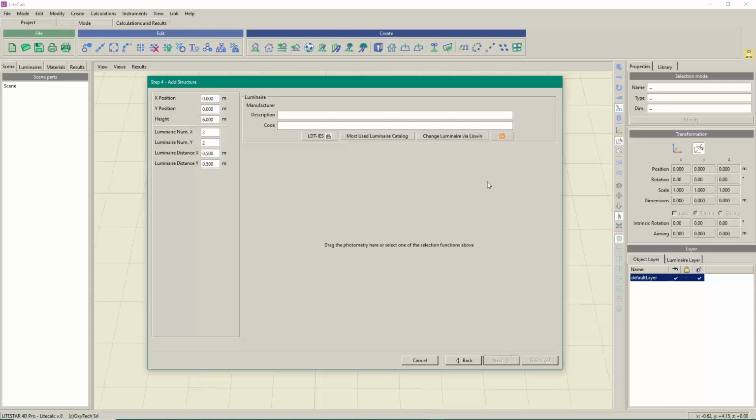So you can place the luminaire exactly at the proper position in, let's say, an irregular way. And this is very different from our old program, where you could have a group of luminaires exclusively in a panel of a high mast. In this case, you could only place the luminaires in rows and columns, and it was fixed. As we are going to show you now, with this program, you are free to place the luminaires at the high mast the way you want to, depending also on the 3D high mast,